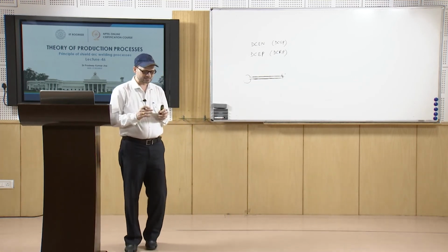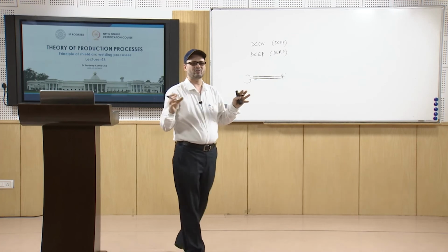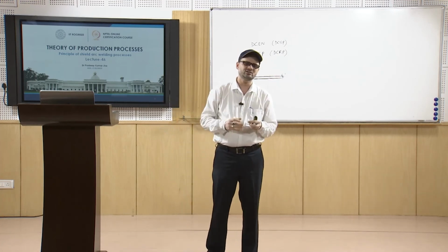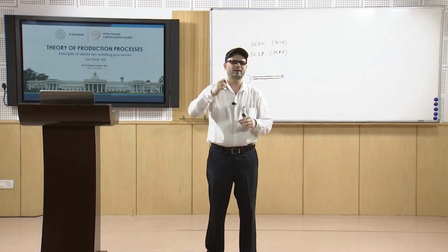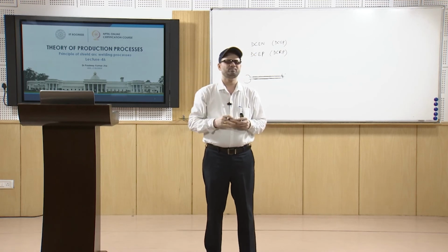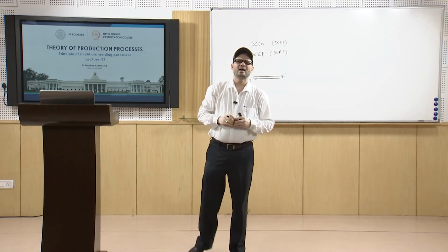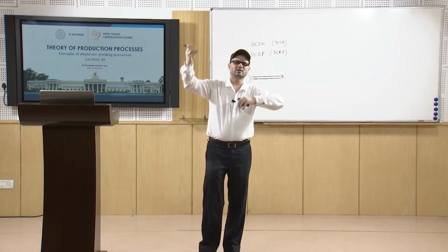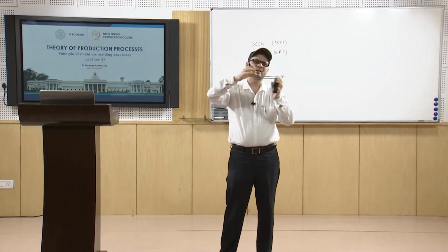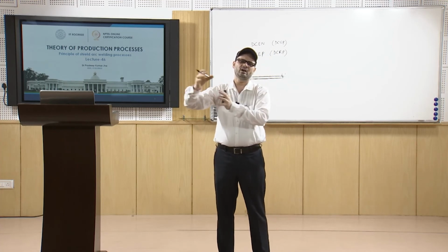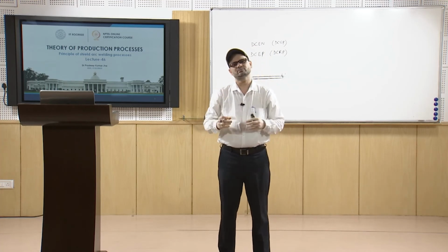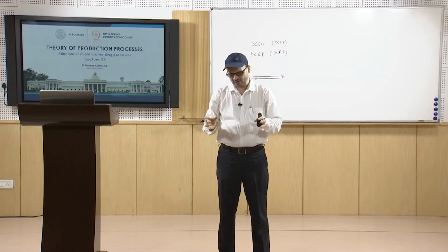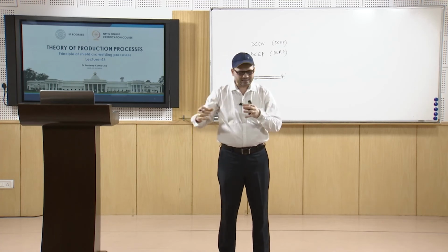Now, in this case, since we are using granular flux from all the sides, we are using the bare wire. The holder, or the mechanism by which the wire is coming, can be moving as the welding progresses, or the work on which the welding is going on can move.